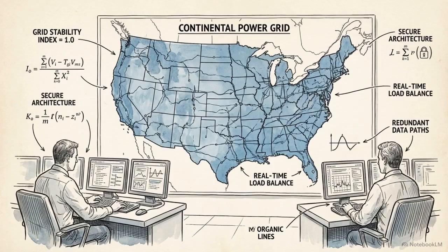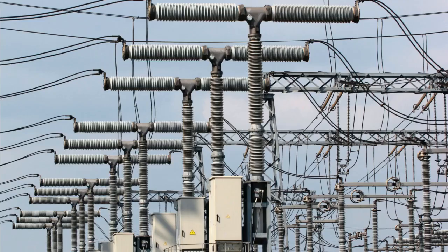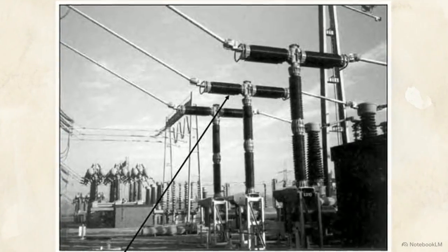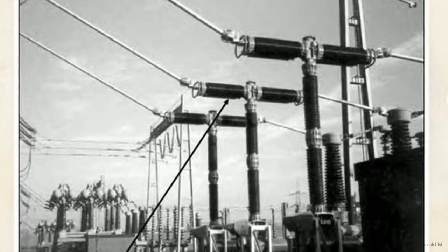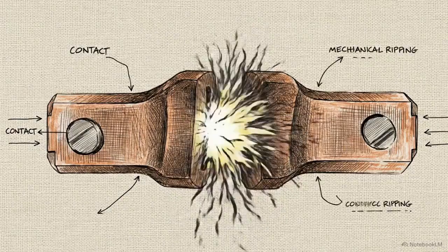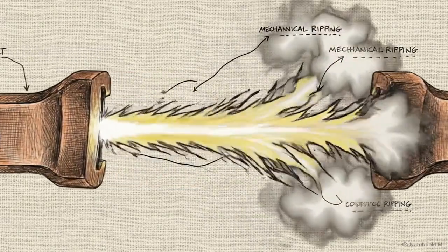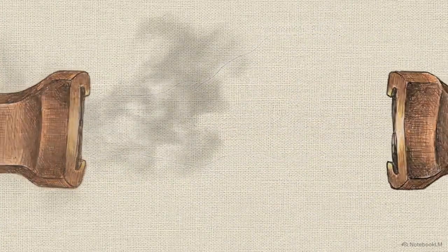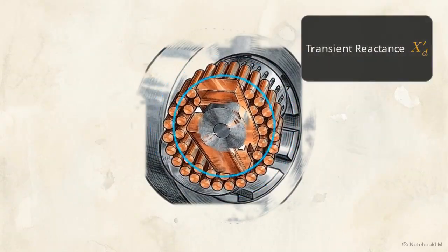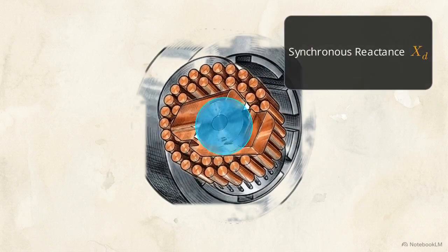Modern power systems are engineered to prevent a fault from ever reaching the steady-state period, avoiding total voltage collapse. Substation protection relays are programmed using the specific subtransient and transient reactance values of the local generating stations. These relays command the circuit breakers to mechanically open their contacts and quench the fault arc entirely within the narrow transient window. The heavy interrupting capacity of these breakers is explicitly sized to survive the brutal peak currents dictated by the machine's subtransient reactance. A generator's shifting internal magnetic layers dictate the precise behavior of every fault current.